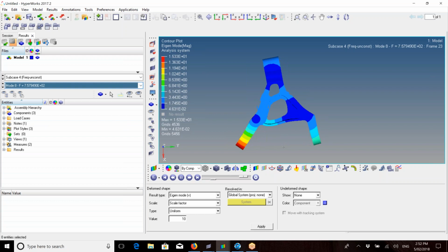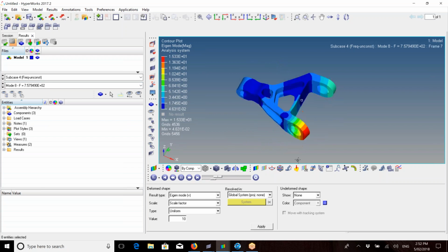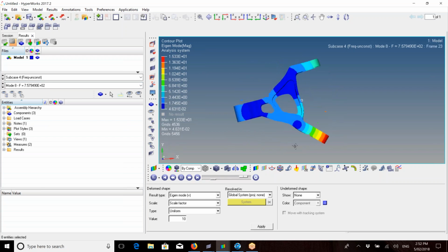As you can see, it's quite different, and we're seeing hotspots in much different areas. So again, this is another really good point to make sure you understand, because the resonant frequency is actually a first failure mode. Then we've got our yield stress, which is a second failure mode, and then the buckling, which is considered a third failure mode. So with these, we want to make sure that our resonant frequencies are far above any frequency that they would see during an in-service life. So we're going to pause that. Now we're going to have a quick look at the buckling.